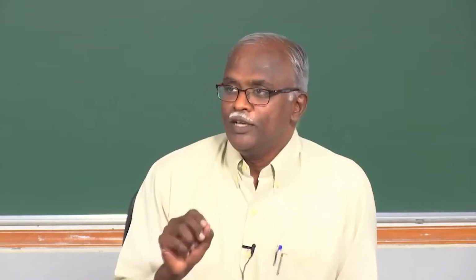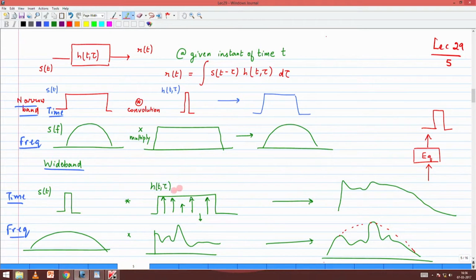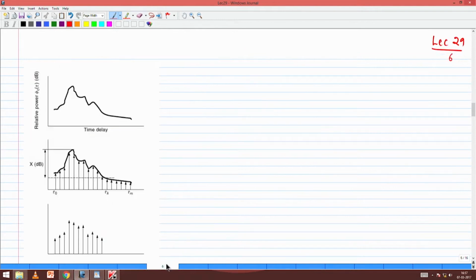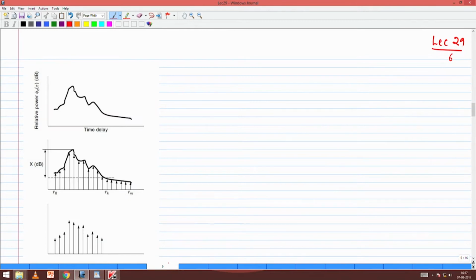This is how we study it in digital communications. The only difference in a wireless channel is that this distortion keeps changing as a function of time. So your equalizer also has to keep changing, because it has to adapt to the distortion and undo the distortion at every stage. So that's a very good summary of the different channels that we have encountered so far. From a practical standpoint, I'm sure that when you get a chance, you will read Molisch, chapters, Appendix 7C.